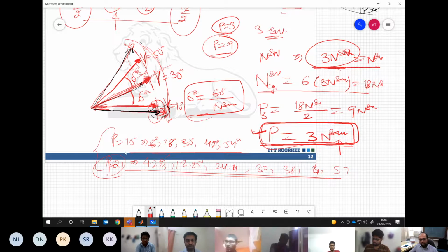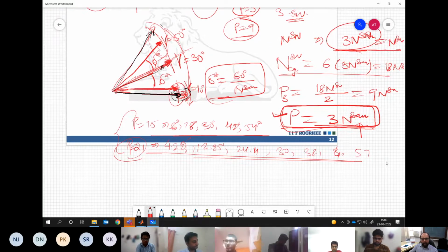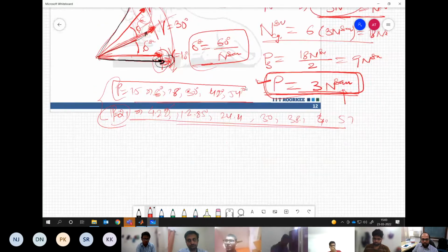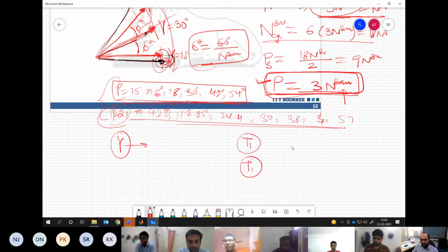So the meaning is, now if you see the gamma value, which means the value of the sector angle at which the samples are located, this is fixed for every sector. Which means that for every sector, our computation of T1, T2 and TZ is going to remain the same. You understand my point? Say pulse number 15 I am operating, and for sector 1 my samples are located at 6, 18, 30, 42, 54.